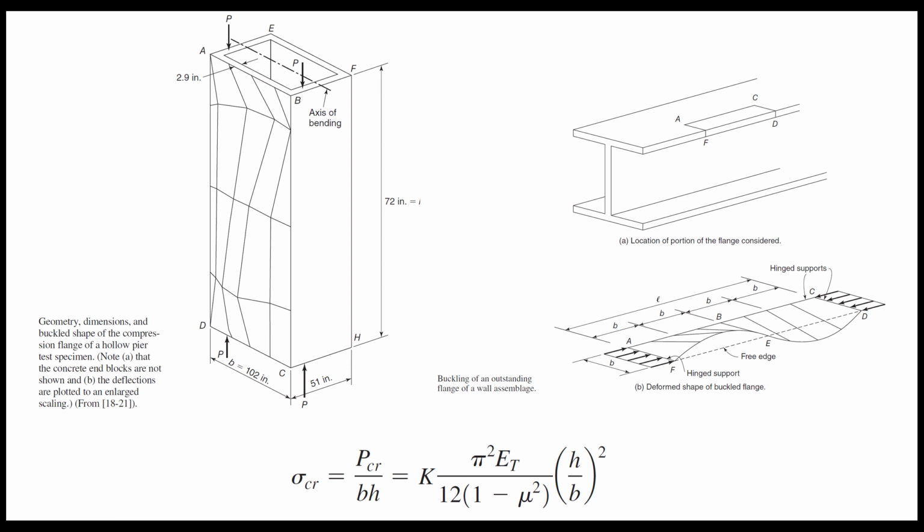This is the reason why the line element is suitable to model the structural column as long as there is no local buckling. However, there is a price to pay when a structural engineer chooses to use a line element for the column section that is thin and long. The later section of this video will explain how to compensate for the inaccurate structural stiffness of the line element with a column shape that is thin and long.